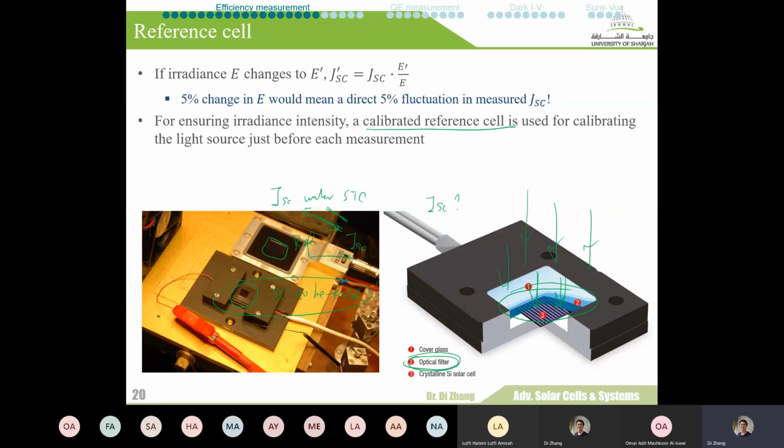Is the wire resistance, let's say, less than 5% or 10% of the solar cell resistance? If that's the case, then typically it's not a big issue. But you are correct. The wire resistance and the connection resistance are also factors we have to consider if we want to do absolutely precise or correct measurements. So that's a very good point to bring up.